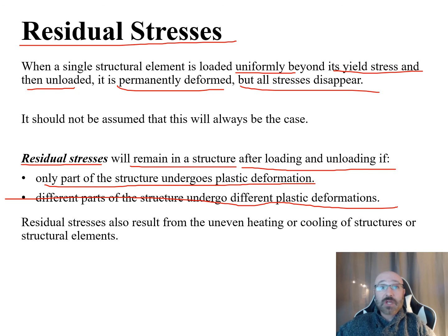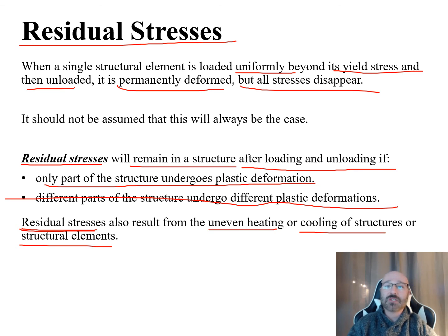These residual stresses can also result from uneven heating or cooling of structures or structural elements. So this is something to consider. Some of these parts are going to be heat tempered or cooled in a bath afterwards, so there may be residual stresses already in some of the parts you'll be using. That's something to consider further along in the design process as well: are these residual stresses in the materials for the components of your design project going to be an issue? So that's something to think about when you're talking about tempering, heat treating, and cooling of parts.